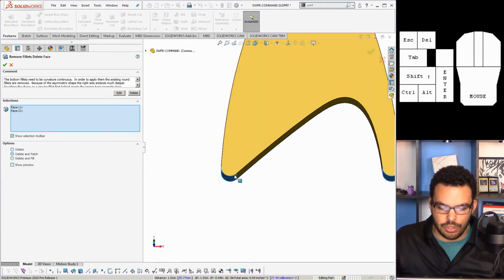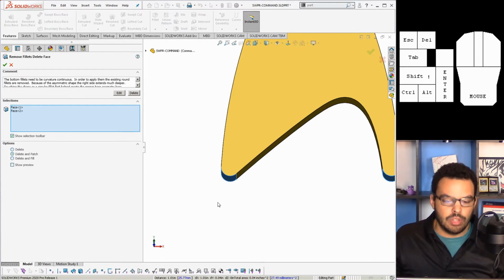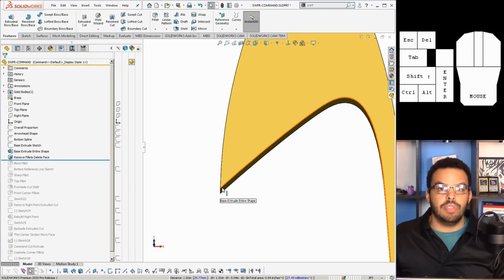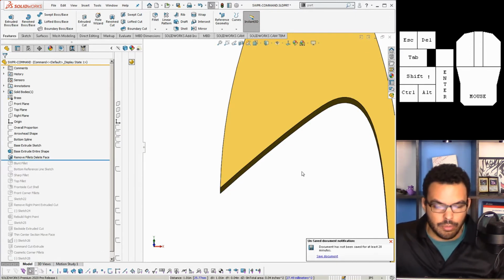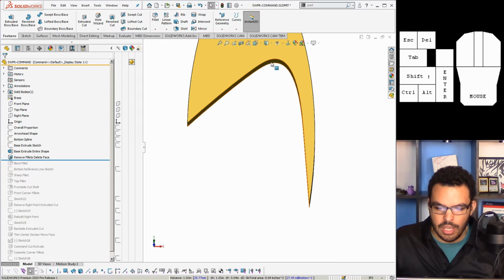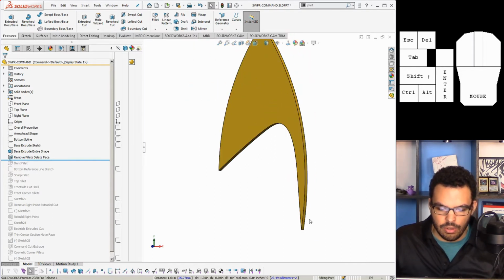So if you imagine there's a virtual sharp here that is not showing, with delete and patch applied to a fillet, you can actually obtain the location of that virtual sharp. It's a powerful tool, as you might expect. And in this case, the virtual sharp goes way, way out here. It just keeps the equation of the spline going, and it just so happened to end over here, which is probably too much, and he's going to trim it.